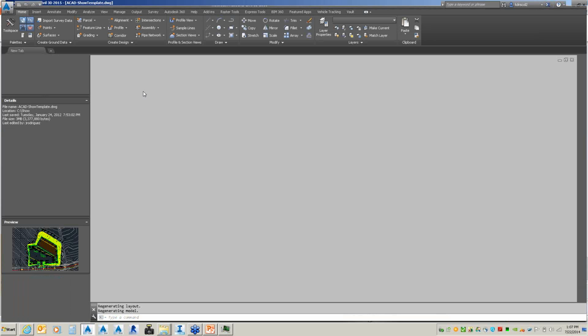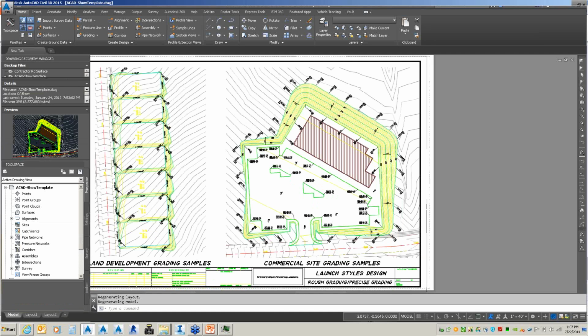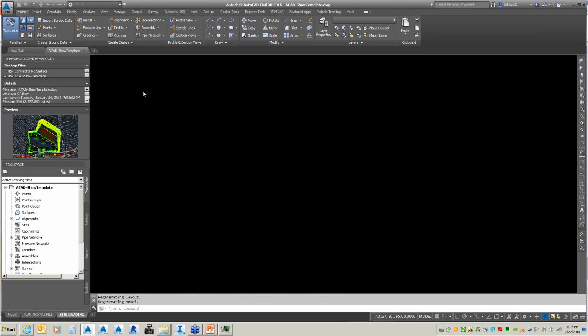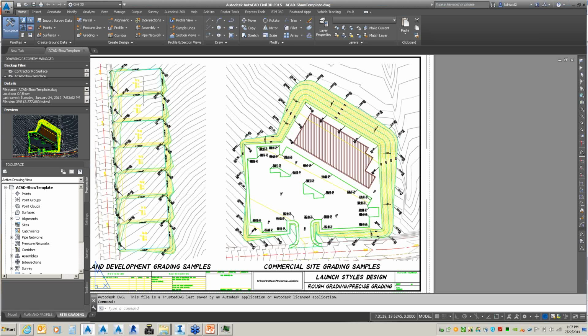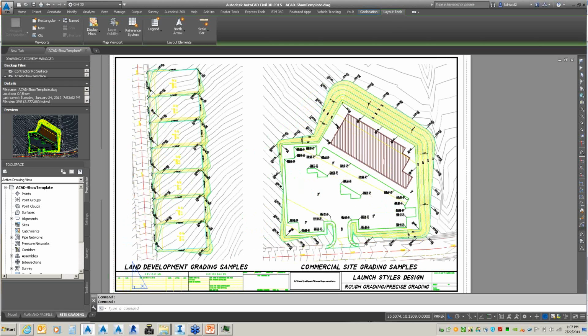Yes, so the profile really manages settings and things like that. Now let's say specifically if you wanted to use a specific ribbon, or you didn't want to use ribbons, you would be making reference to a CUI file, and the CUI file can be exported from a previous version straight into Civil 3D. So you can do those things also.